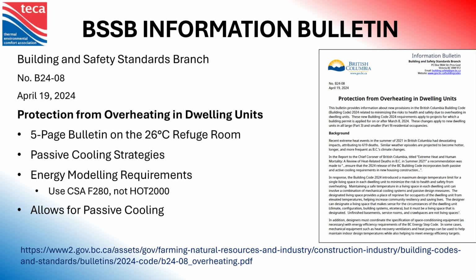The best piece of information I have on this is this Building and Safety Standards Branch information bulletin. They released this on April 19th, 2024. I highly recommend you read it if you haven't already. It mentions things like passive cooling strategies, which is really mitigation for your cooling load. It mentions you're supposed to use CSA F280, not HOT2000 for your energy modeling. And it does explicitly state that passive cooling is allowed.